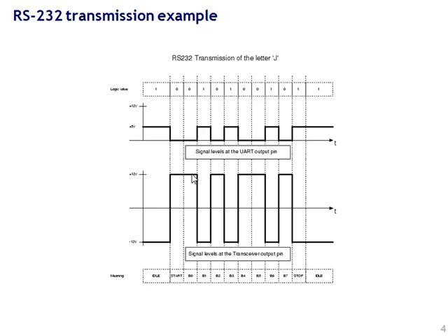And then you'll wish you had a parity bit, which determines whether you've got an error in the transmitted data word. Parity allows for the detection of a single bit error. And they're writing this as plus minus 12 volts, although I think nominal it's plus minus 10 volts. So when you transmit without a separate clock, you've got to have some way to encode the clock so the transmitter and the receiver can synchronize.